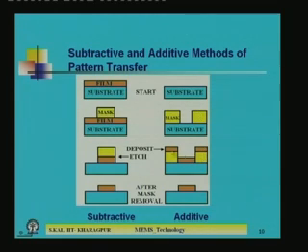This is the film thickness, the red region, it should be smaller than the mask, means photoresist thickness. Okay. So, that means the thickness of the photoresist should be large, large compared to the film thickness. Otherwise you cannot go for the lift-off technique.